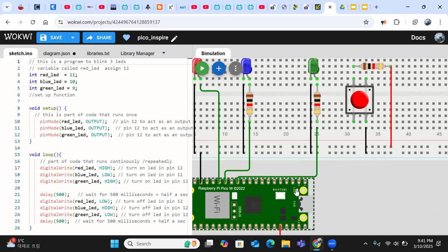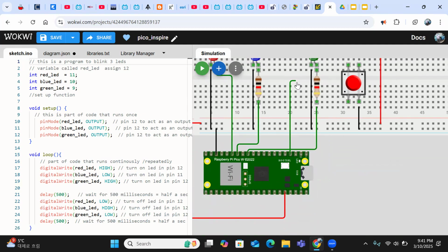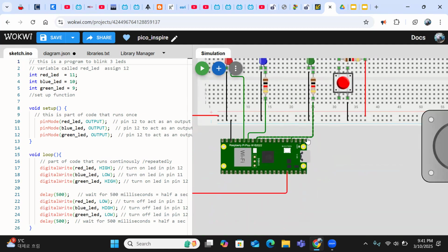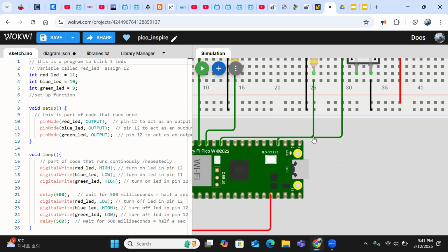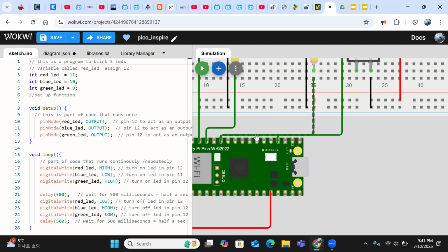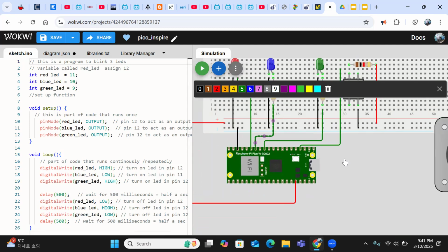Then I want us to use a GPIO, like GP2. Can you see 2? Yes. And then we connect it here to where the 2 meets. How do you know? You can choose any. You are going to write it in your code. This is GP2, so you are going to write it here in your code, okay?